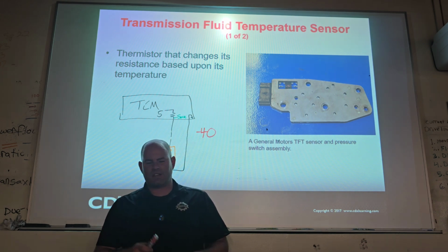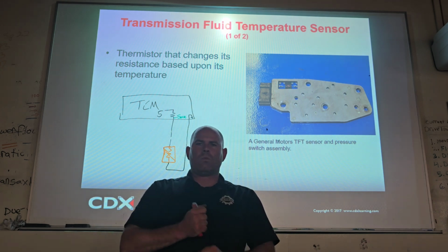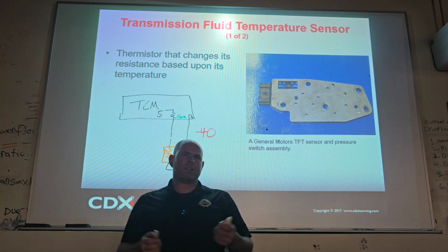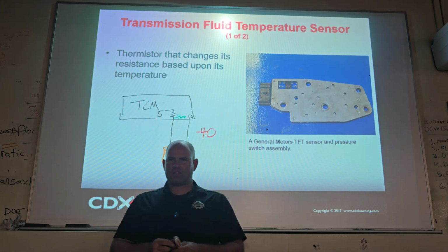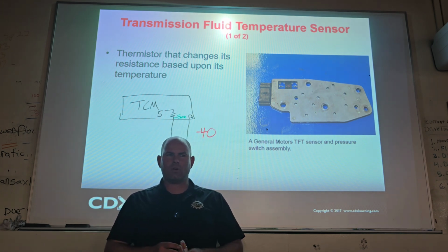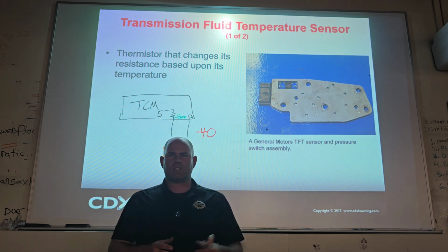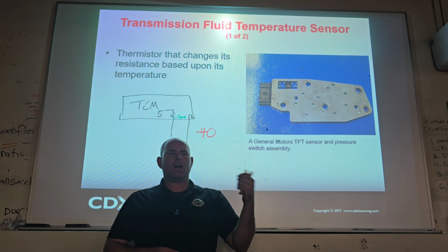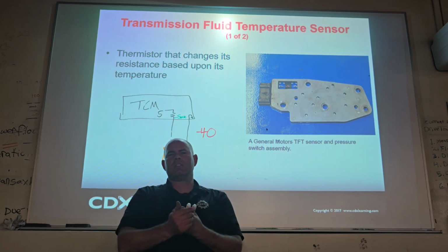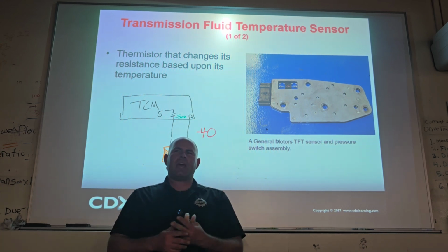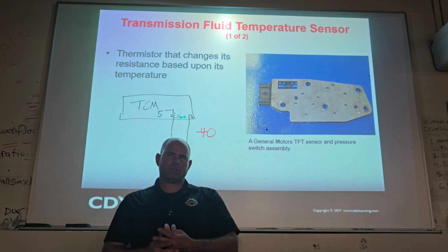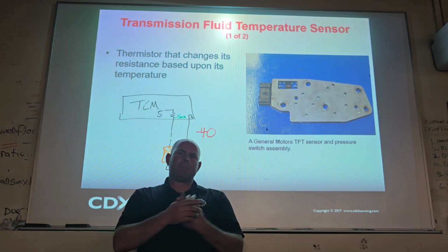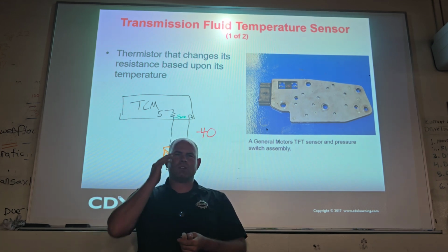So he asked, what should this guy do? And I just said, well, it's an electronically controlled transmission, so it's going to be either an input problem, right? Inputs are sensors. A processing problem, which would be the ECU. Or an output problem, and the outputs are shift solenoids. The processor is the ECM. But the inputs, there's a bunch of different ones.